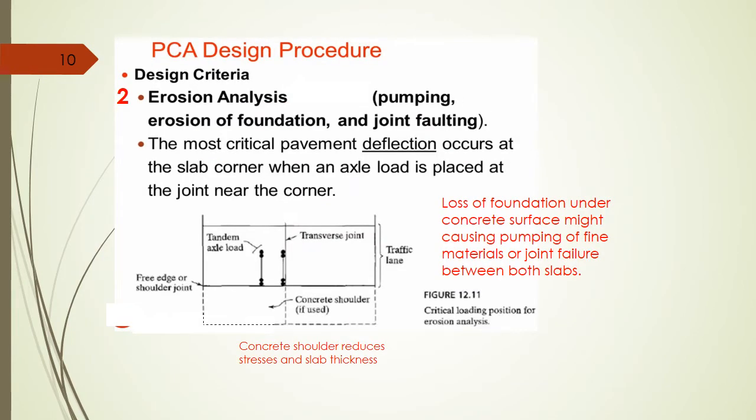Second design criteria, erosion analysis: pumping, erosion of foundation and joint faulting. The most critical pavement deflection occurs at the slab corner when an axle load is placed at the joint near the corner.